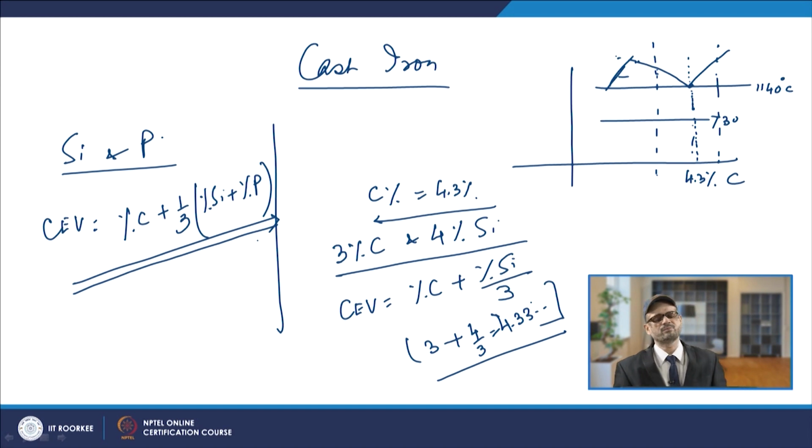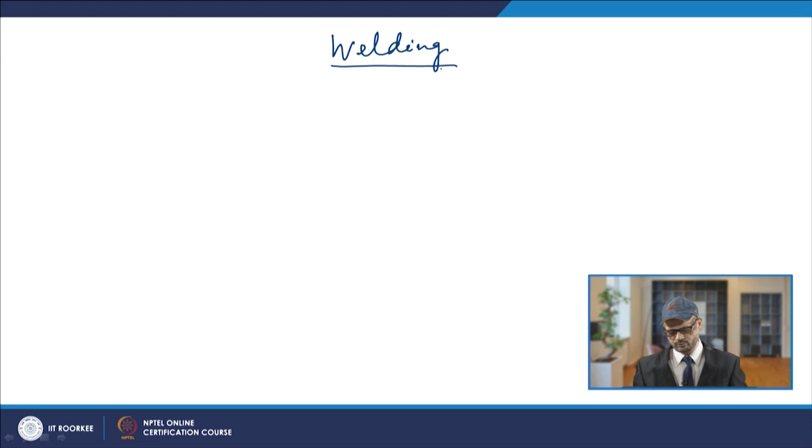Now, if you talk about the use of carbon equivalent value in the case of welding, many a times you may have to go for pre or post weld heat treatment. So, you may have to go for preheating or post weld heat treatment, and that depends upon the carbon equivalent value. If the carbon equivalent value is more, then for stress relieving, because there will be a chance of cracking.